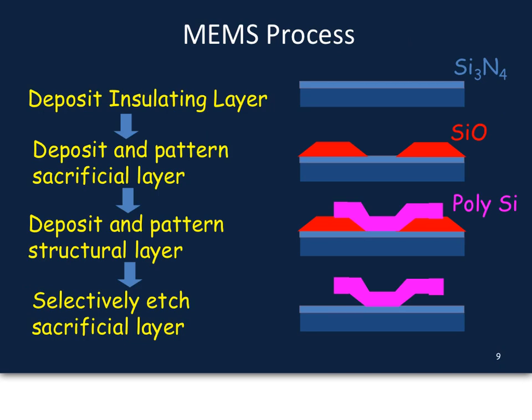So again, unlike microchips, MEMS devices require the development of elevated structures, right? Microchips all have devices laid flat on the substrate. So how do we make these elevated structures? Well, to create suspended structures such as wires for a wire anemometer, remember that's a flow sensor that we talked about previously, we need to deposit and pattern a so-called sacrificial layer, on top of which we will deposit the materials comprising the suspended structure, and which will then be eroded away underneath that structure.